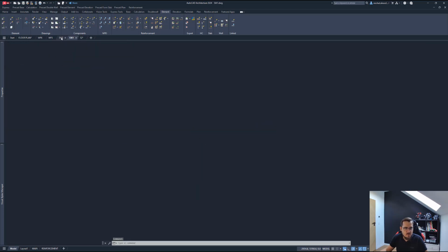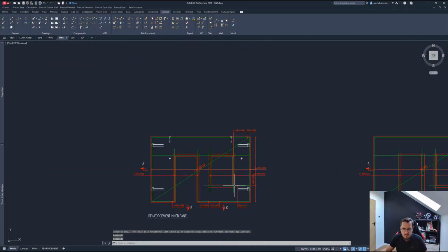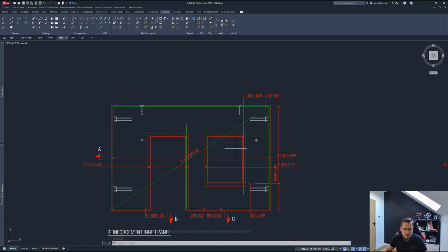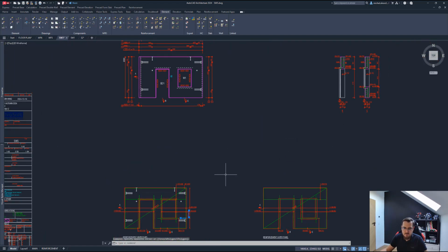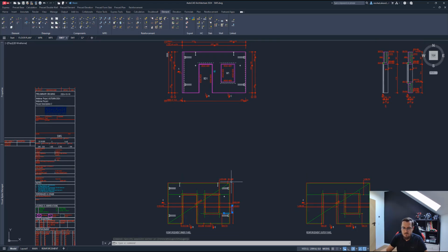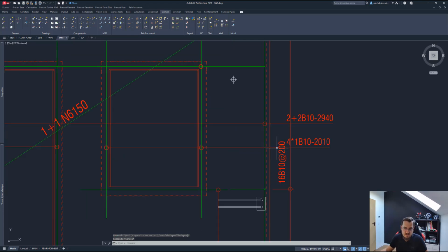So to quickly demonstrate the drawings that we get. All right, so here we have a bunch of stuff. Immediately on the drawing, there's some reinforcement that's shown. There are custom materials that were placed in that wall automatically while we were creating connections, and we also have that edge reinforcement that's been created, right? We can convert that to a reinforcement group, or we can leave it as is, as 16 B10 bars at 20. So we specified that distance of 20 centimeters, 200 mil.